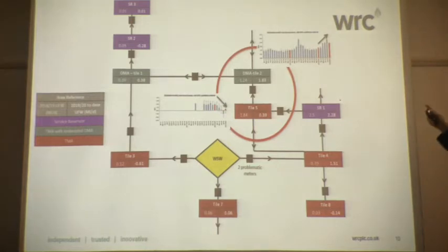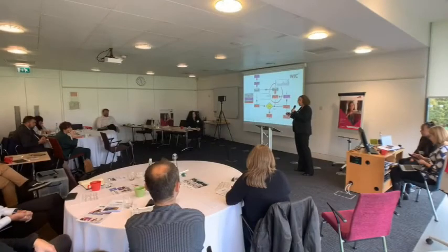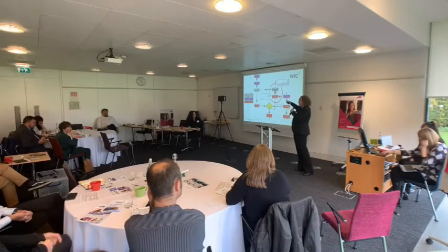Now, that piece of insight led us to say, we're suspicious of this meter. We think that meter is not recording correctly. And sure enough, the water company went out, looked at the meter, and it turned out it was drifting. The performance was changing. I don't know the cause of that, but they have now rectified the situation and brought down their DMA leakage, causing much cheering amongst them because it was quite a significant volume. And they can accurately work out now what that DMA leakage is. But they'd spent 4 months chasing mythical leaks in a DMA, crews out sweeping, looking for leaks, because they hadn't got that other side of the meter issue.